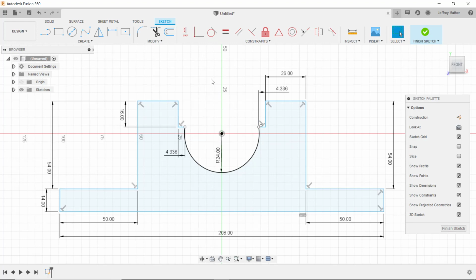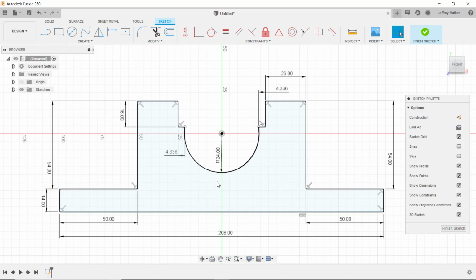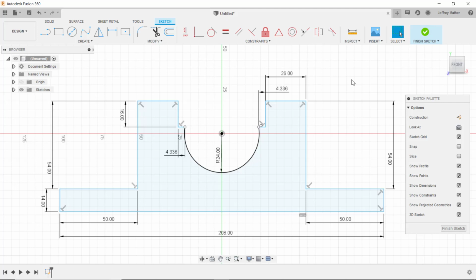In fact, I recommend that beginners start with either one circle or one line or one rectangle and constrain it immediately. Make sure that it turns black, letting us know that it is fully defined. And then do one entity at a time. Don't draw 15, 17 entities, whatever, without having them constrained. Do one at a time, constrain each one.